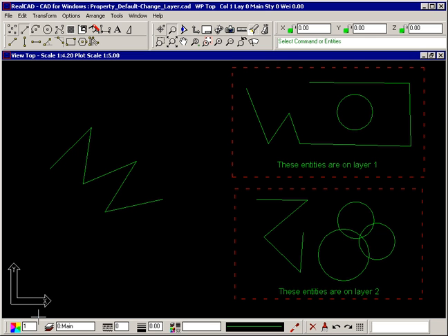When the current layer has a name associated with it, the name is shown here next to the layer number. You can even set the layer by simply changing the number shown here if you remember what number it is. You must press the Tab key to activate the new number, and you can't change an entity's layer in this way. That completes this tutorial.